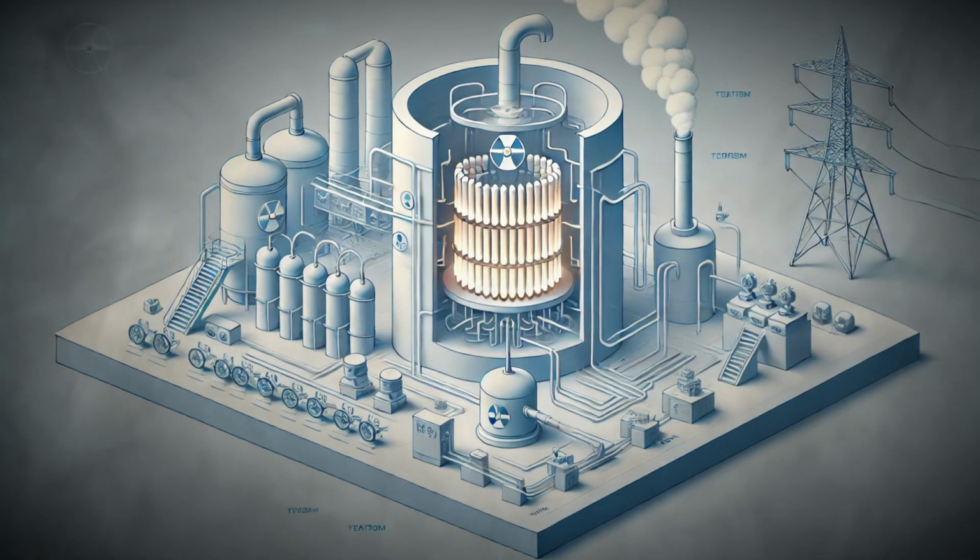The effectiveness of the coolant depends not only on its ability to absorb and carry heat, but also on the continuous circulation driven by powerful pumps. If the pumps fail, or if coolant flow is interrupted, the temperature inside the core rises quickly, which is why backup systems and emergency core cooling systems are always part of the design.